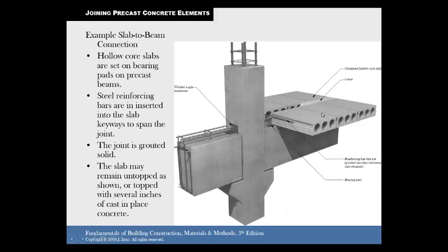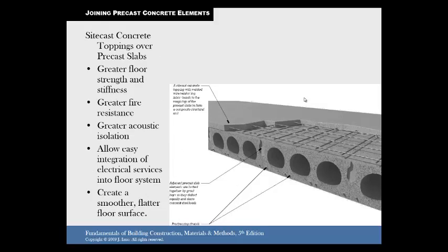And then you got your floors, precast floor things that rest. There's a little weld plate there, or a pad. Reinforcing bars will go across it. They'll rest on here. Then your grout will come in, and that will cover up all of the stuff sticking up, so that it'll become one cohesive piece, because the rebar's going that way, rebar's going that way, and the grout is like the glue that holds it all together. And then you might even come in after that and put a thin layer of lightweight concrete to make one smooth floor finish, which would really give it some structure.